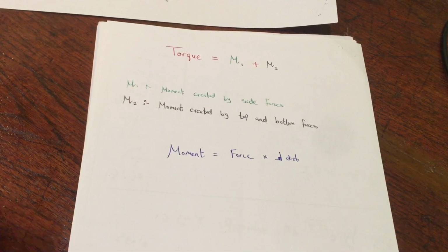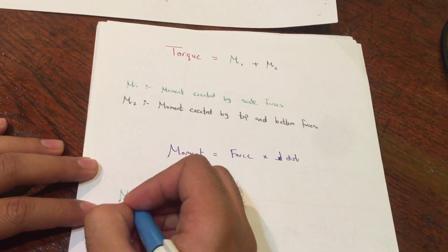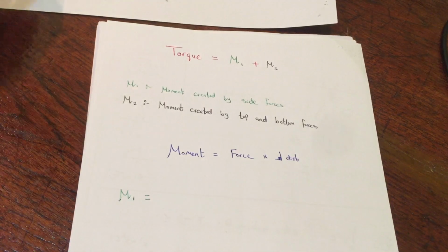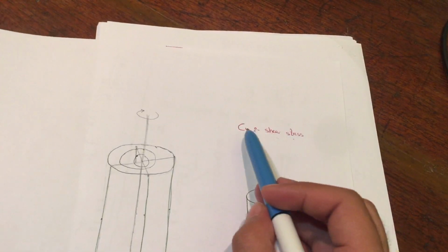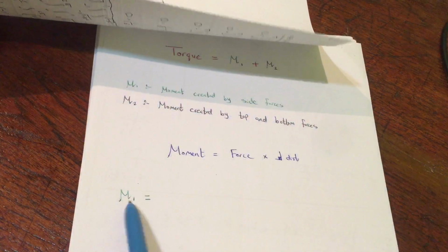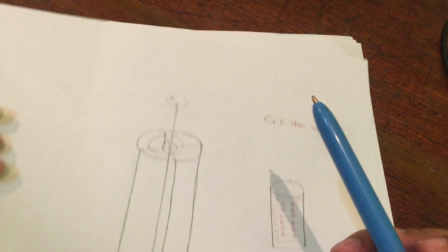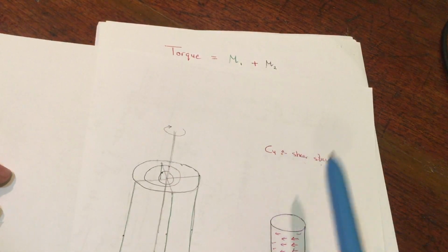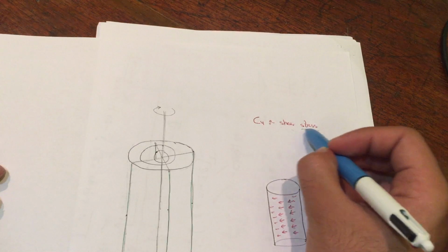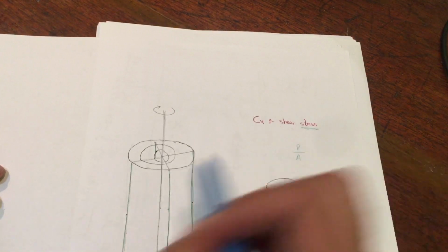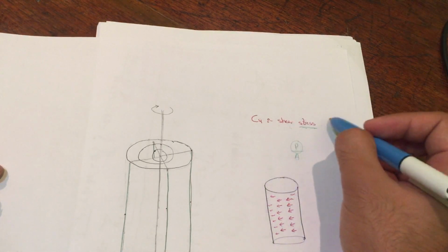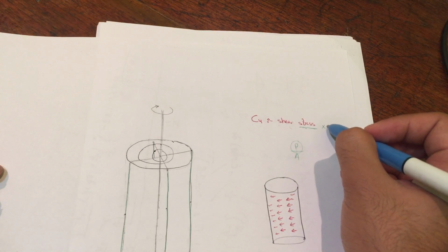So when we work on moment number 1, here as we know, we have our Cu as the shear stress on the whole surface, and the green color is talking about the side forces. This shear force is distributed on the surface of the cylinder, and as we know, any stress is the force over the area. So if I am going to get only the force, I'll multiply the stress by my surface area.